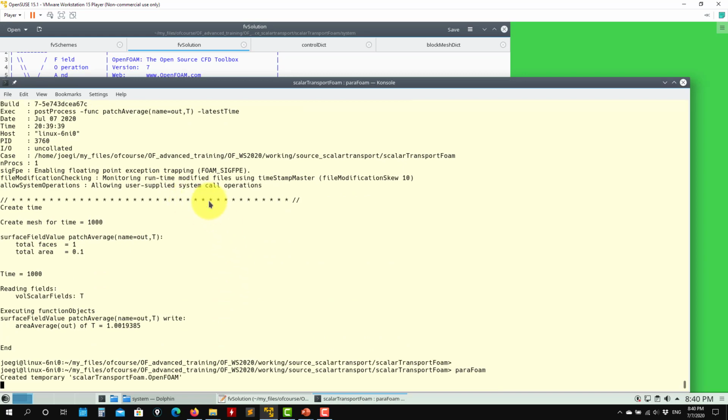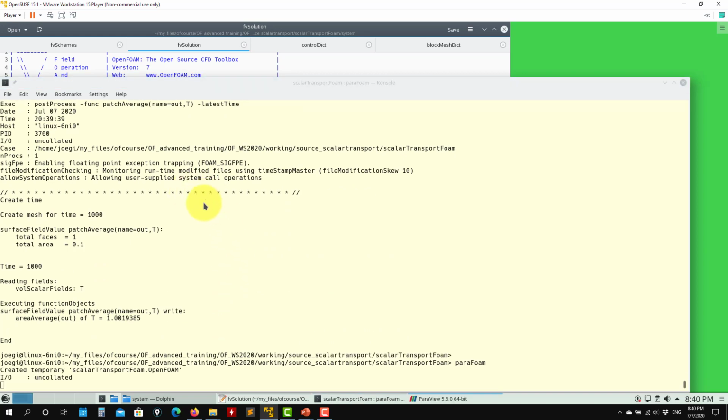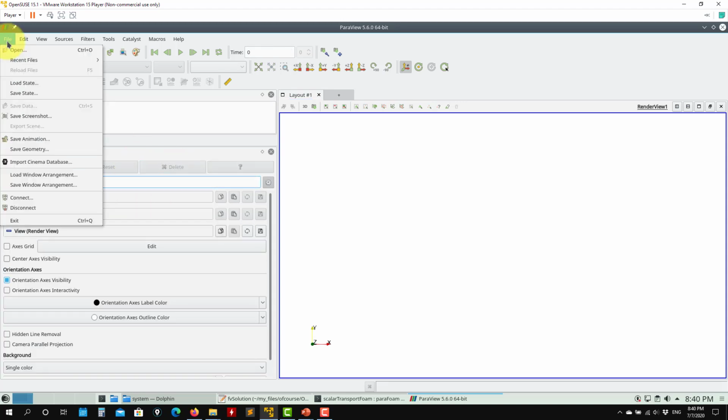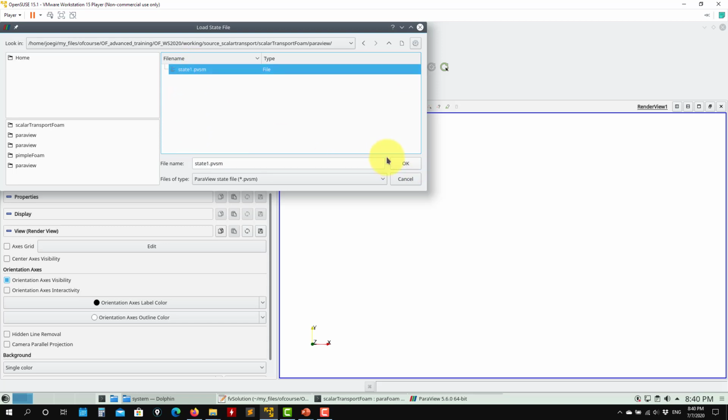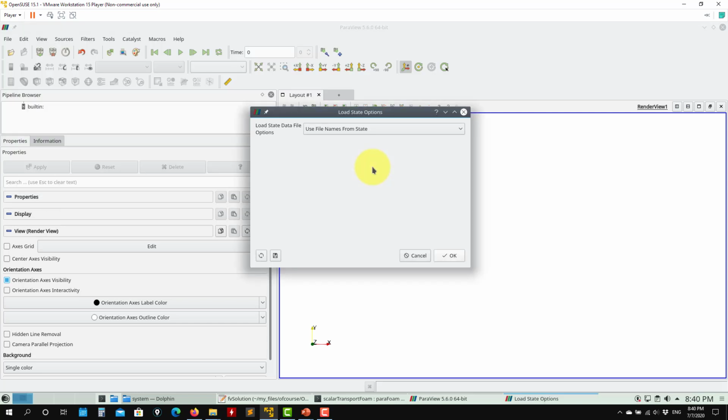So if we visualize, sometimes these methods require that you use a small variation of the solution. So that means small CFL number at the beginning or small under-relaxation factors at the beginning, and then you can increase that under-relaxation slowly.